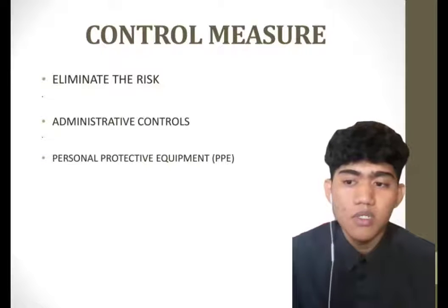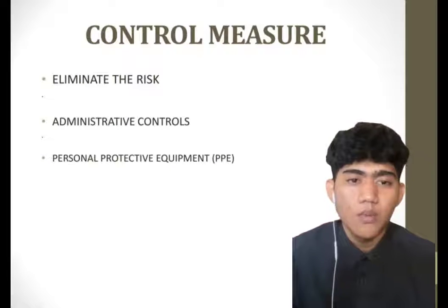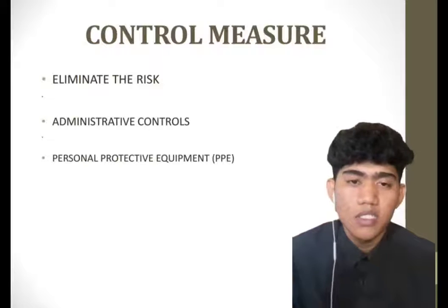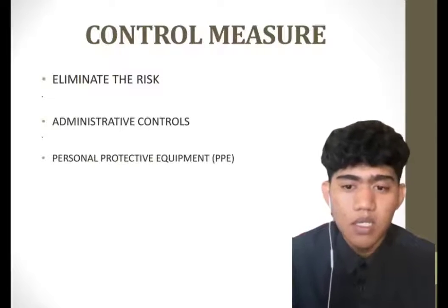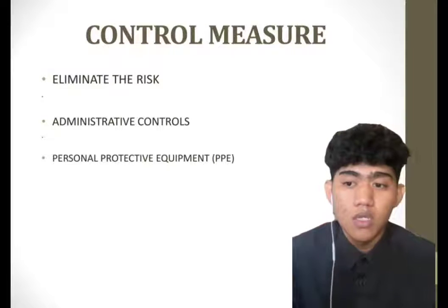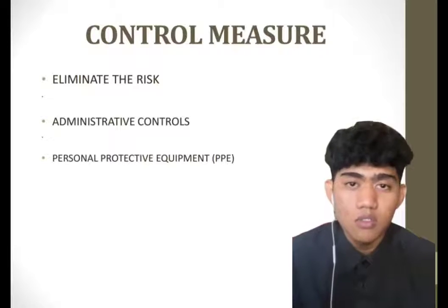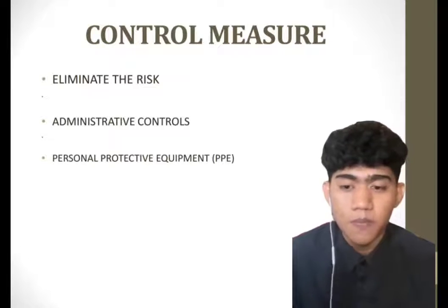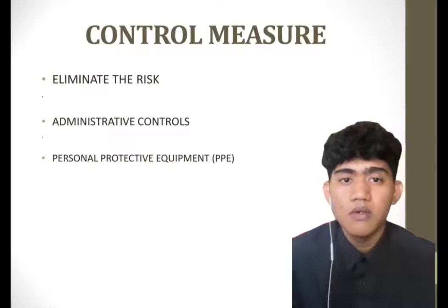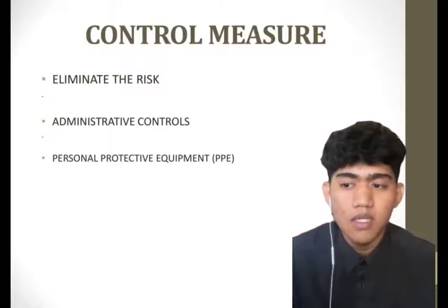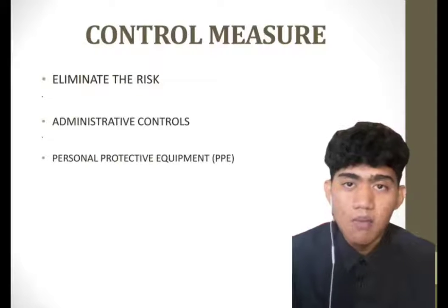It should be worn at all times when operating a forklift. Fourth, hearing protection. This is because forklifts can operate in very noisy environments. Therefore, earplugs should be worn to protect against hearing loss due to noise. And lastly, proper footwear and a seat belt should be used anytime the forklift is in motion.